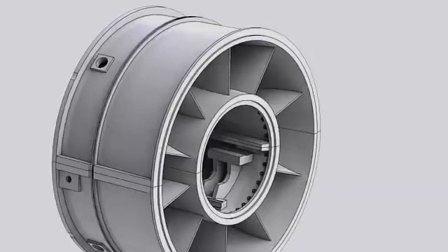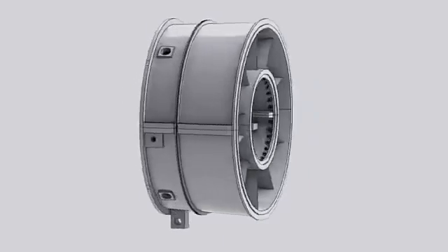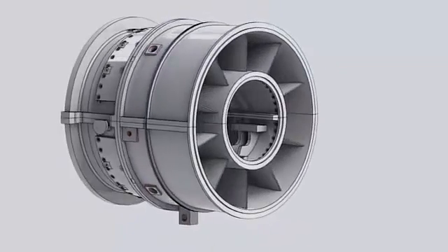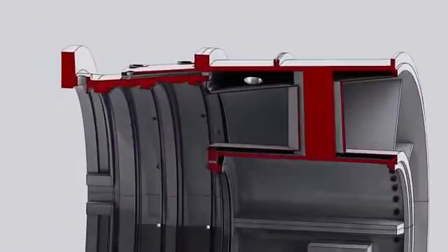This stability is required to keep the exhaust frame inner cylinder, which carries the bearing number 3, in the accurate position, avoiding any misalignment. To ensure the temperature stability, air is forced by means of two off-base blowers between the exhaust frame outer cylinder and the exhaust frame diffuser surface through 4 ports. A portion of this air goes to the cooling holes around the turbine shell, and the remaining air flows between the struts and its outer airfoil-shaped fairing surface.